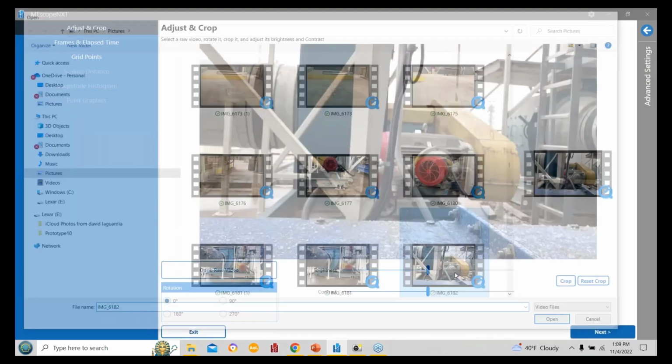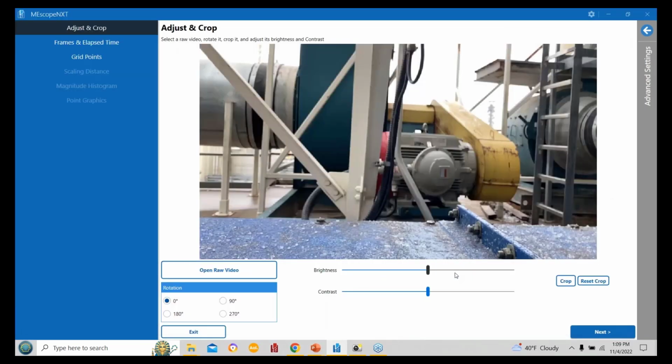I'm gonna drop this in. You can see off to the side, there's some duct in front of me here that's blocking a little portion of the frame. Couldn't avoid that. This is a belt-driven motor fan system. The motor is 1780 RPM. The fan is 1670, I think, RPM. So there's a couple closely spaced peaks there. And it's an interesting machine.